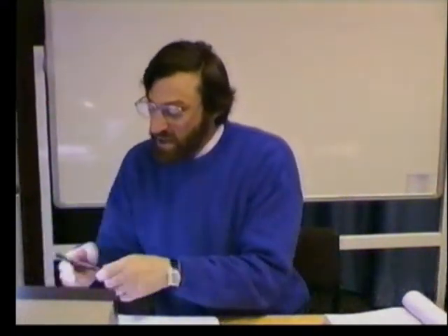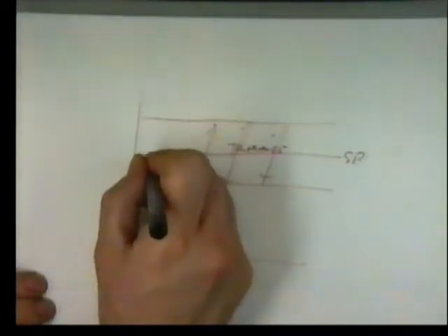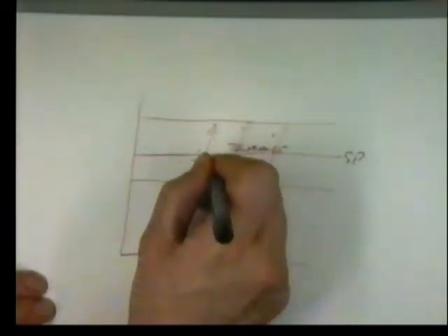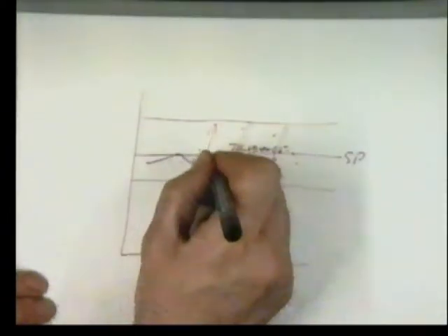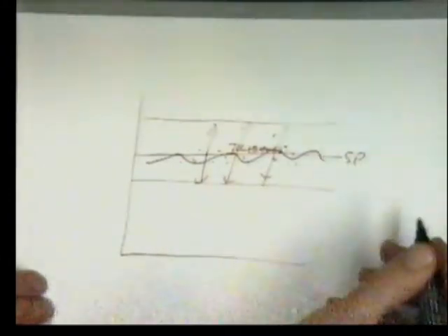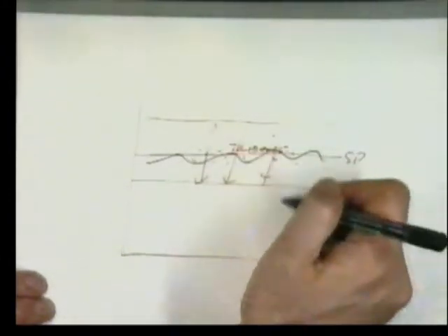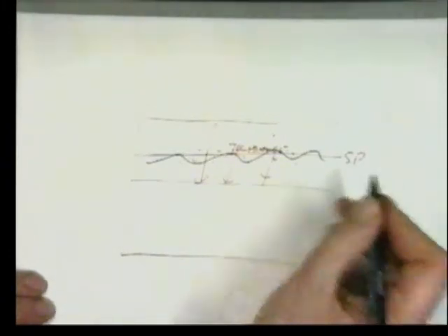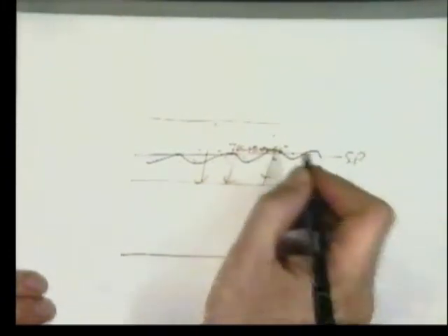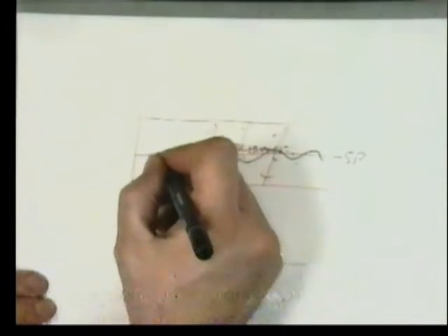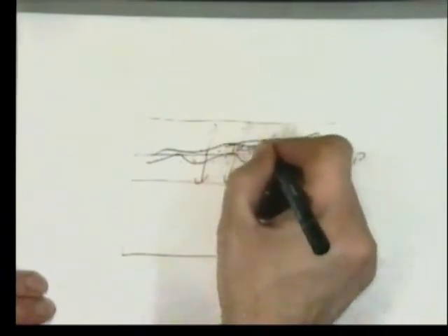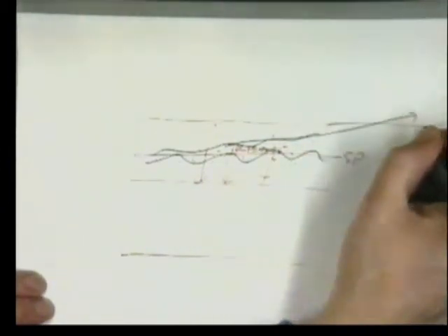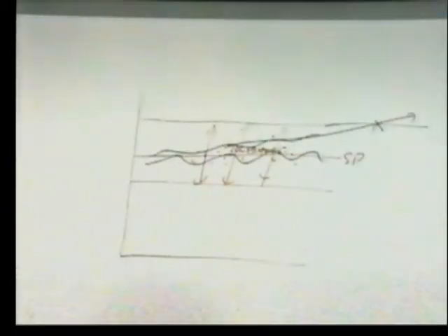So what we will tend to do, you can go into factories and see these things, is we build up graphs. We say, over time, they were all generally around about here or here, and you tend to get these trend graphs. And you actually see them in factories where they average out the readings. They say, as long as the product is within the tolerance band, that's fine. The whole idea of SPC is that if you do this, you should be able to predict trends such that you can predict sometime in the future you're going to go out of tolerance.